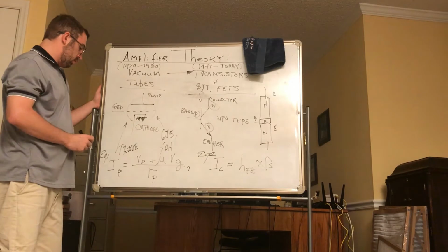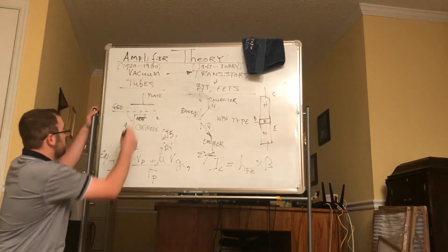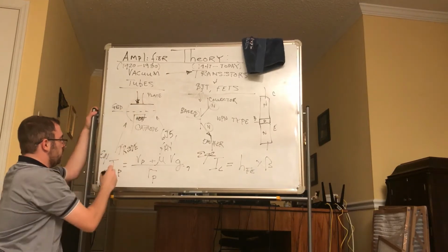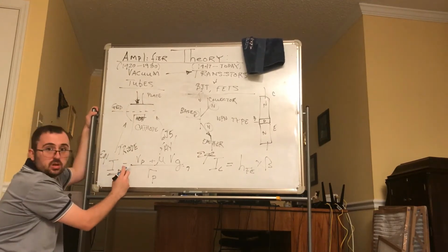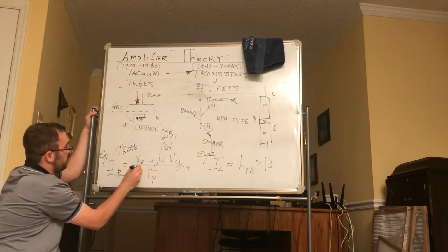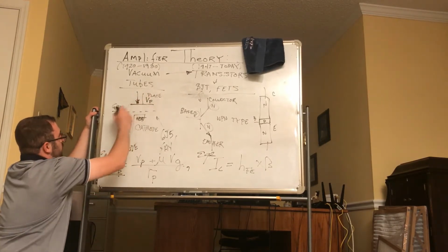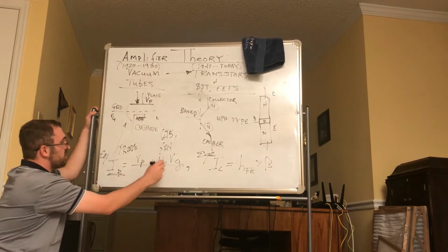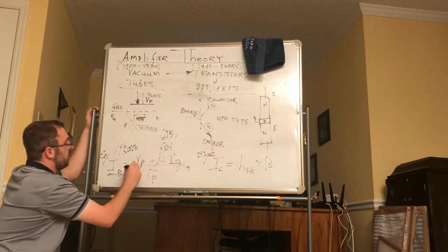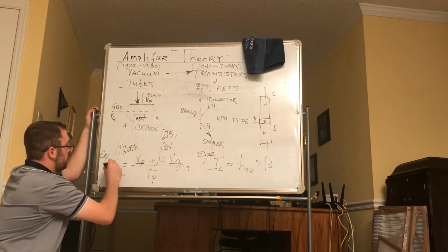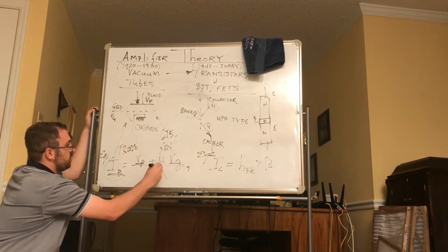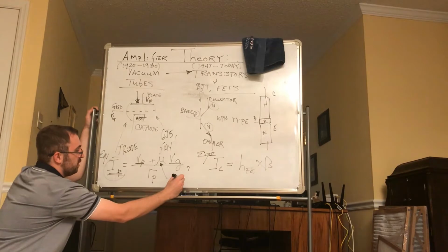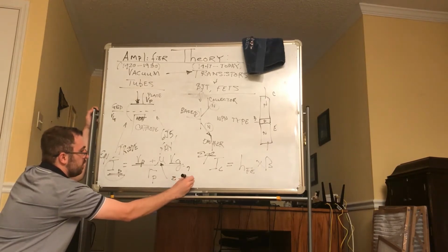And what happened is the current that would flow in this direction classically was governed by this equation. The voltages are referenced to ground. It's the plate voltage, which would be here, the grid voltage here, and so basically there's a tug of war between the grid voltage and the plate voltage, and it controls the plate current. This value is mu, which was typically between 2, believe it or not, to about 200 max.